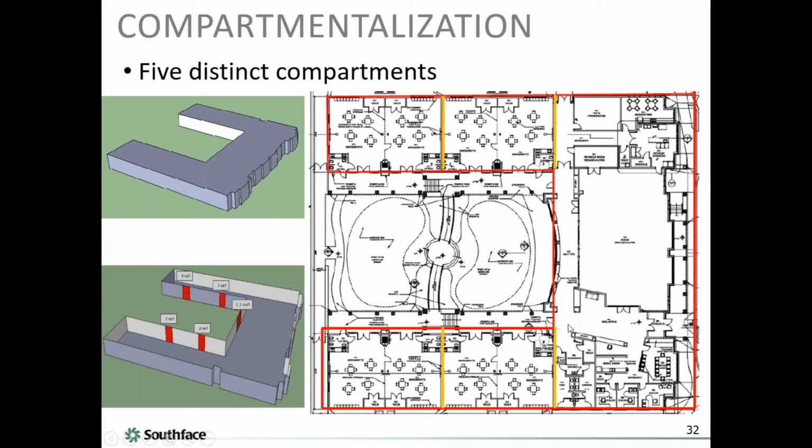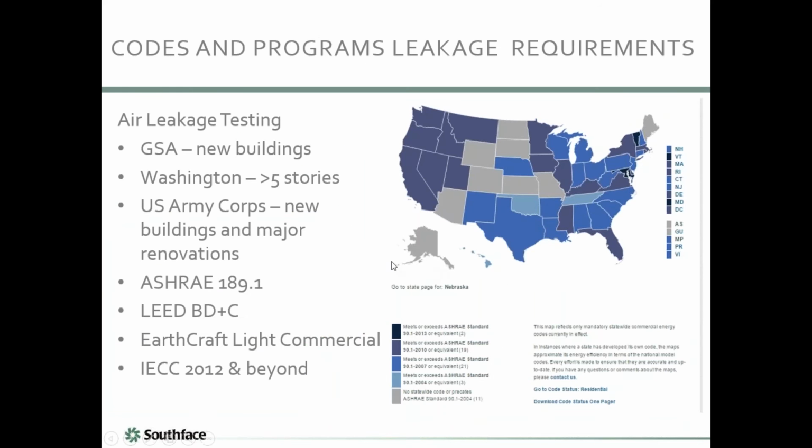And we've also found when you get to a little bit more complicated buildings, it's nice if you can have someone that's a whiz at Google SketchUp, and you can kind of figure out where you want to put your blower doors. And in this case, I think it was pretty obvious. We had a courtyard here that we could have them all face. So communication amongst each of the zones is important, and we'll get more into detail. But anything you want to add on that? I think this is one where we kind of really learned the lesson about just sending the right amount of power to each fan, and later on we learned about the sort of the equal pressure trick.